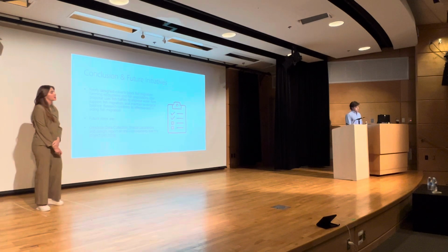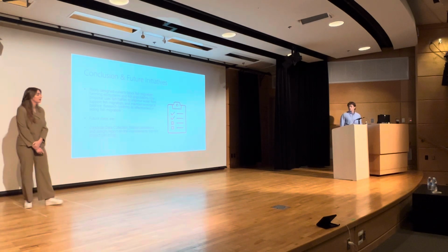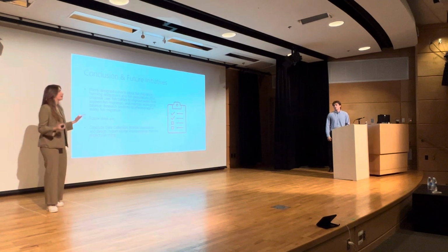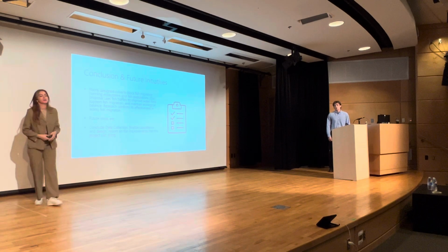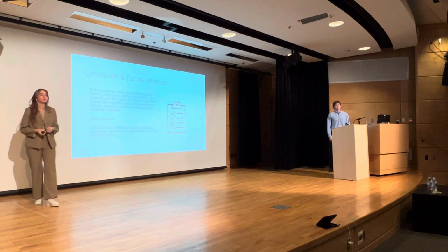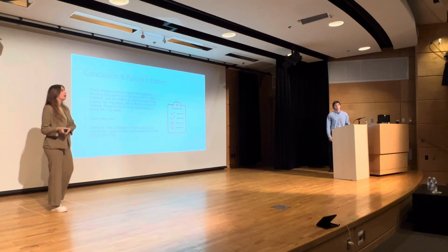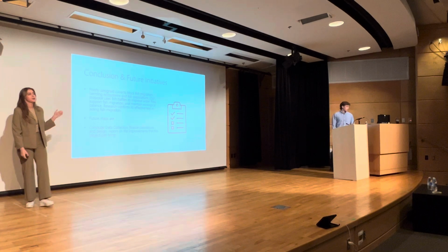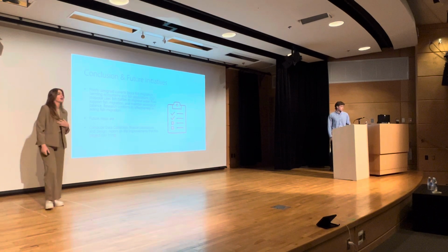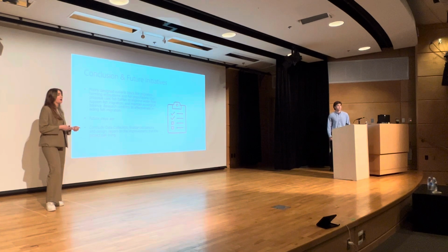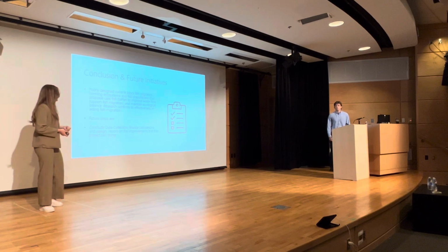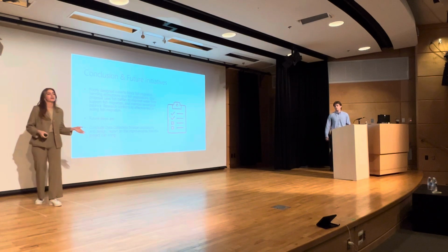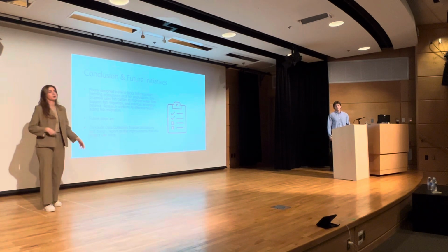So that was our procedure, and this is our conclusion and future initiatives. Poorly designed culverts block fish migration, which obstructs their migration paths. Our solution is to install fish baffles in culverts to reduce water flow and make it possible for fish to restore their natural migration paths. Our research so far confirms that this is effective, and our future steps are to conclude the data collection, start and finish our flow calculations and design, and also report on the improvements that this brought, meaning what difference there is from the existing culvert to the proposed culvert.